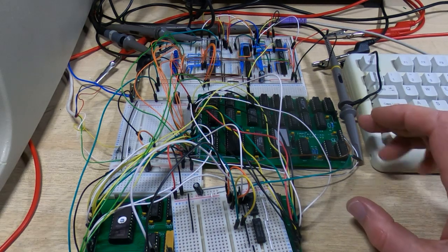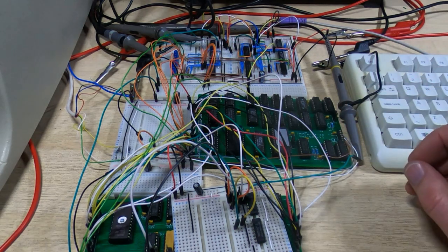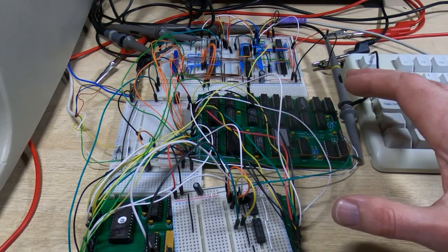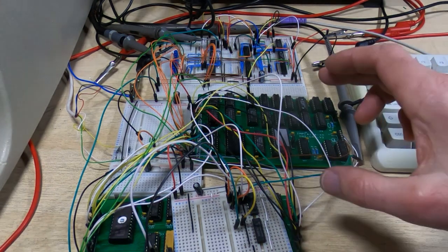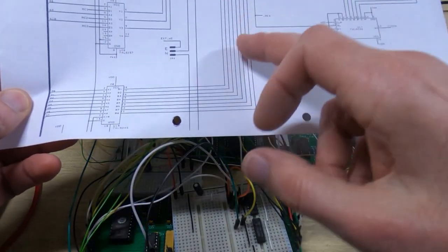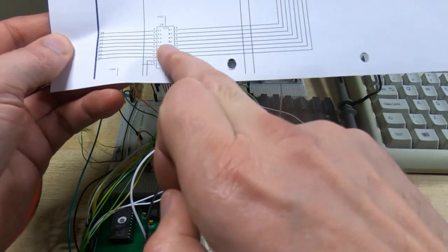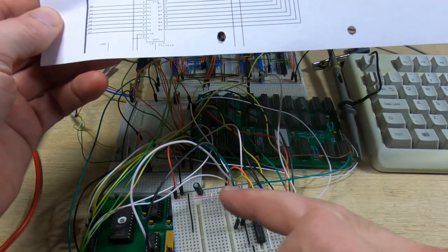Now in reality we kind of need to be able to read the video RAM anyway. Anyone writing any serious software is almost certainly going to want to do that, so we'd probably include that feature irrespective of whether we needed it for the cursor generation at all. So I'd already built that in, and you may recall from the circuits I'd shown previously, let's grab a copy of it, that what we had was a buffer that allows us to send data into the SRAM, so this is a bidirectional buffer, or to read data from the SRAM, and there's some control logic down here.